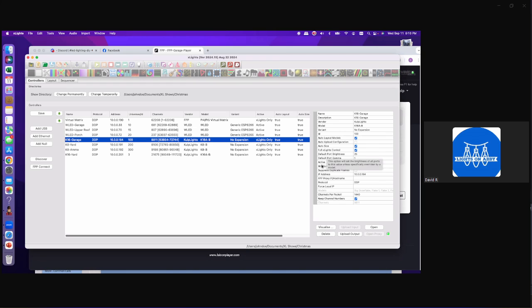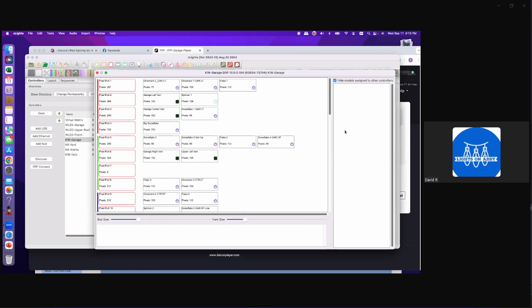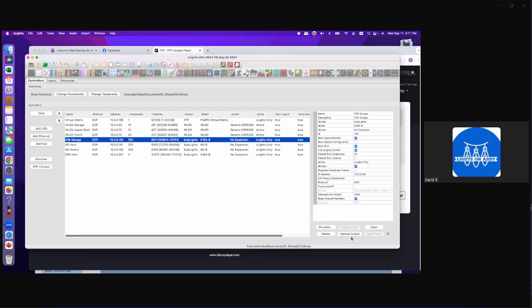from xLights. So in Visualize, the visualizer, if you had available models, you would drag them to the ports, and that would assign the channels for those. As you can see right here, port 1, it tells the pixel number, it tells the channel numbers, it tells how much amp draw is coming from, it tells the brightness. So you would set all your models up on each port and then push the settings to the port with the upload output button.